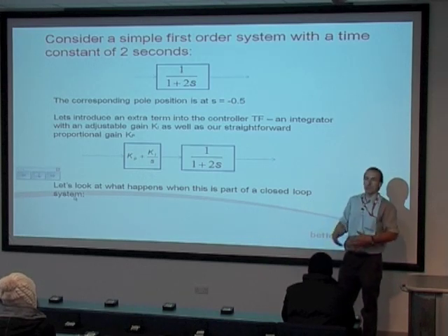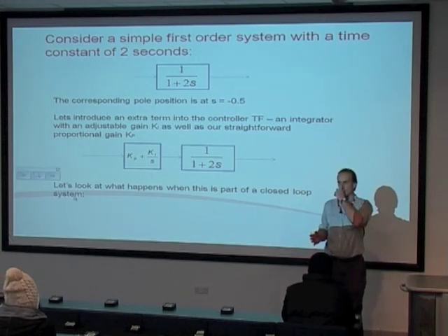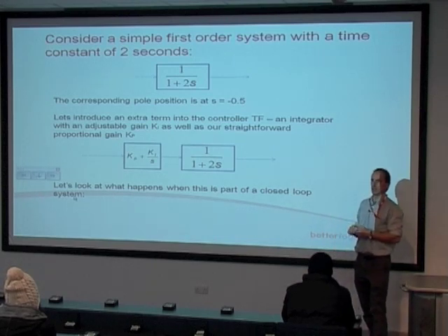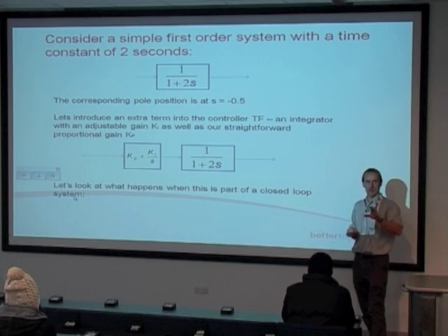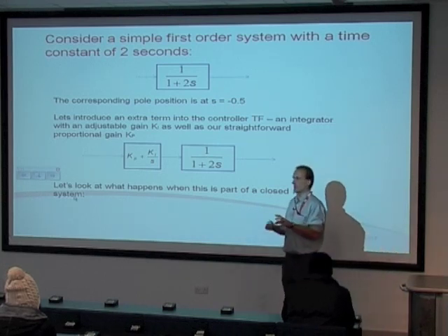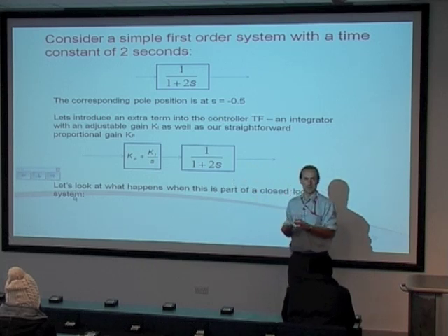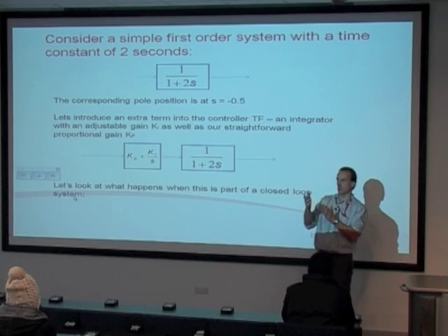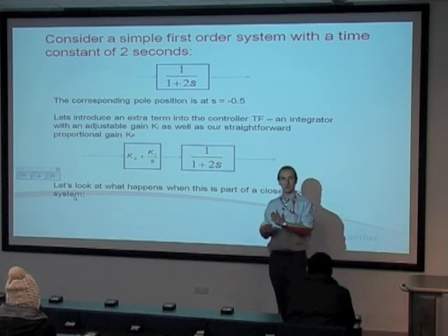And that's going to give a particular sort of dynamic behavior. If I introduce a gain into that system, then effectively what it's doing is it's changing the size of that error signal. If I put in a gain of about 10, then if I'm going a little bit too slow, I get an error signal, let's say 1 mile per hour too slow.